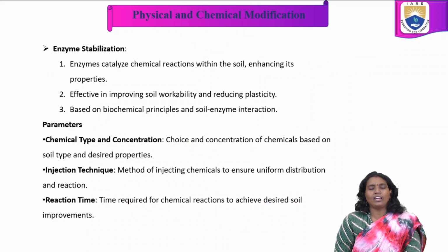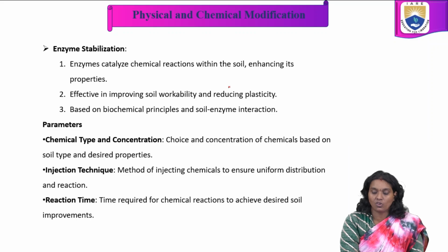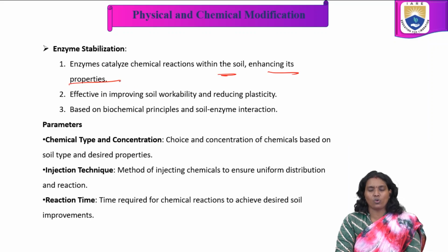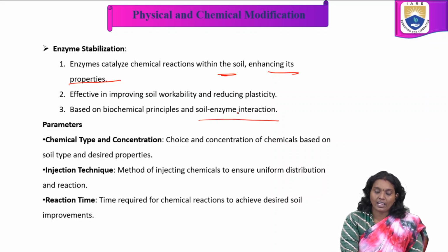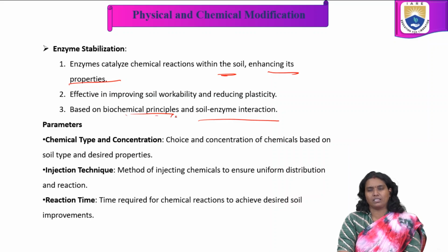Coming to the enzyme stabilization, enzymes catalyze chemical reactions within the soil, enhancing its properties. It is effective in improving soil workability and reducing plasticity, based on the soil enzyme interaction and biochemical principles. In these, the parameters are chemical type and concentration, injection technique, and reaction times.